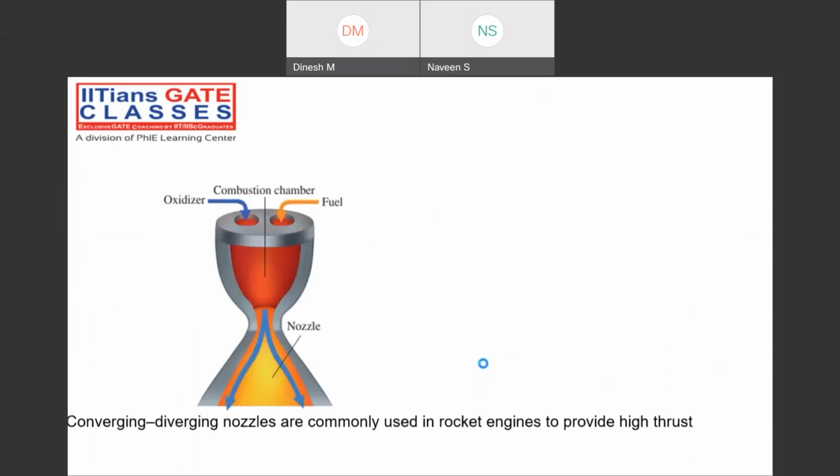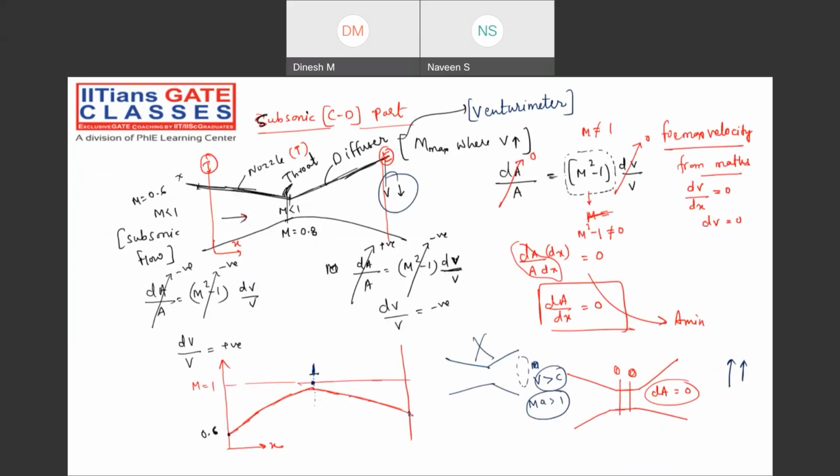I told you, right? See, you are getting this Mach number lesser than the throat Mach number. Who will decide? There's no rocket science going on, right? There's no prediction going on like just by reading any book. It is just happening based on how much back pressure or design pressure you are maintaining at the valve. Understanding my point? It depends on that. If the valve is fully open, then what will happen? The flow will happen like anything. Further, you are reducing the pressure, the flow will happen like anything, such that the velocity will increase and the Mach number graph will be like this. At the throat it will be 1, and at the exit it will be more than the throat.